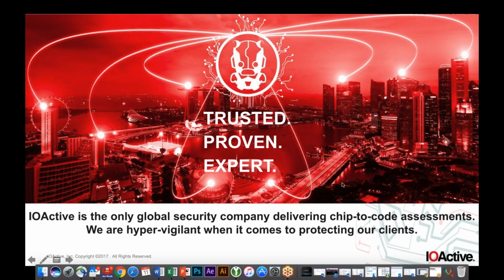Excellent. So data diodes are very, very good pieces of technology that have their place in various different ICS infrastructures. That said, they're not a replacement for certain other technologies such as deep packet inspection firewalls and other application-specific firewalls, because those devices are bidirectional in nature. So depending on the industrial environment, we would want to put data diodes. My personal preference from a design standpoint is multiple diodes lower in the system to protect sub-elements of the process that don't necessarily need to talk out from that environment, but may need to provide data out of that environment.